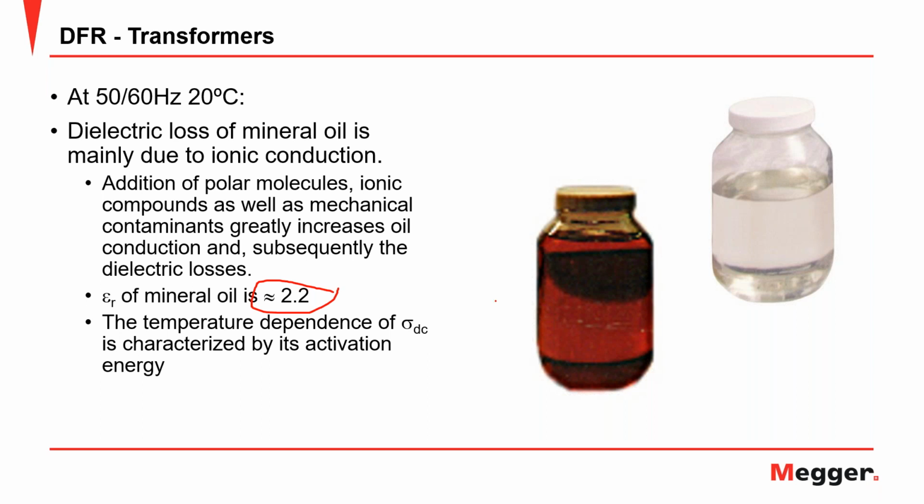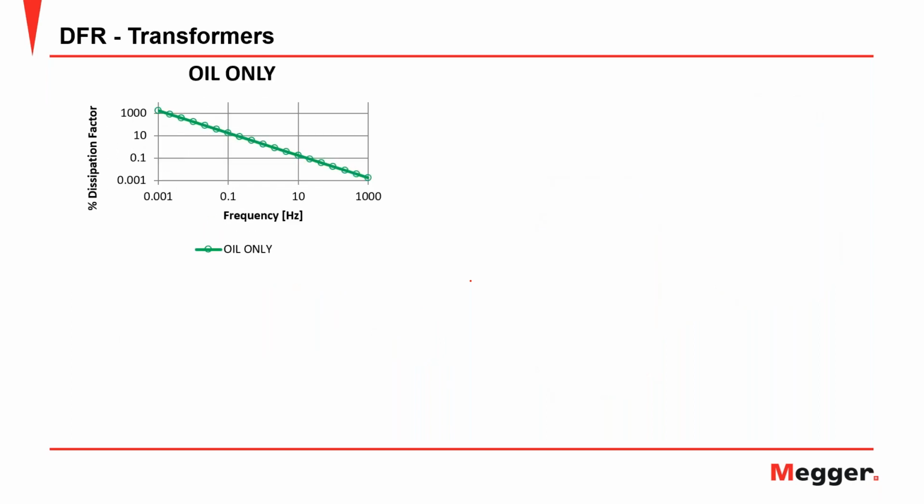And of course, you can see the difference between this crystal clear brand new oil and this oil that might have already gone through quite a few years of service. So of course, the condition, the resistivity and the conductivity, has to change. The properties will change, and this will influence the dielectric response that we look at. With this being said, let's look at the response of just oil.